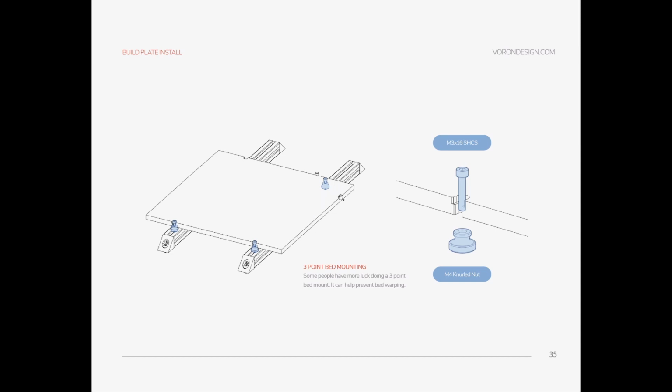I mean, because once you heat an aluminum bed, it tries to expand a bit, and if you tighten both ends, it will not have room to expand. It's very small, but yeah, it can affect your bed flatness. So I think mine is affected.